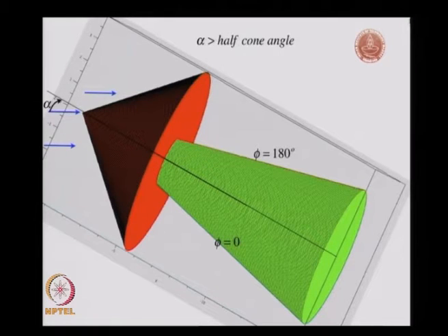So, now what we will look at here. This is S2, and this radial line again projects onto this point. Now, let us look at one streamline. This streamline in this particular case comes from here, which is S1, but it does not merge exactly onto the top of the cone. Because of the larger angle of attack, it does not merge onto the phi equals 180 degrees radial line.